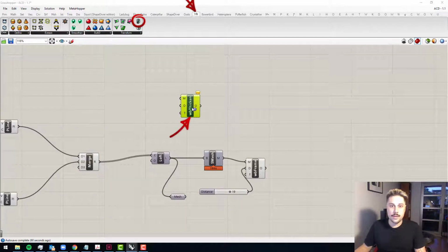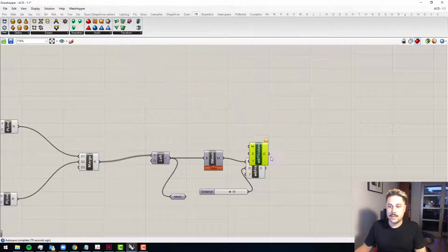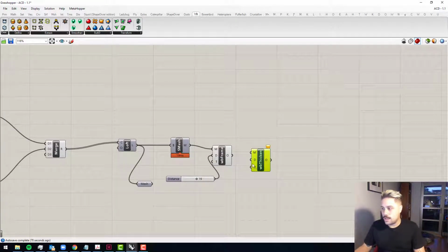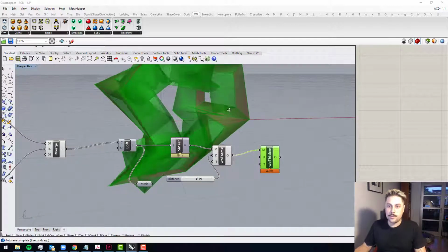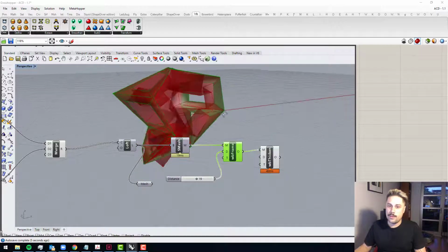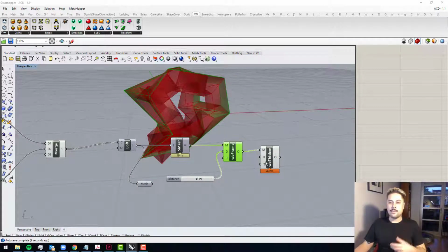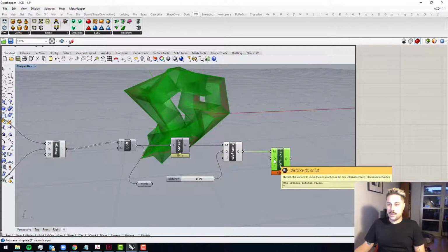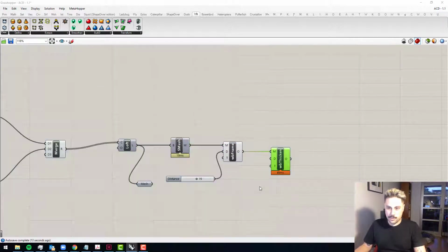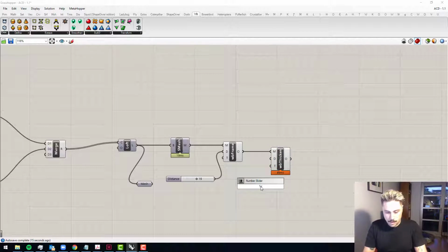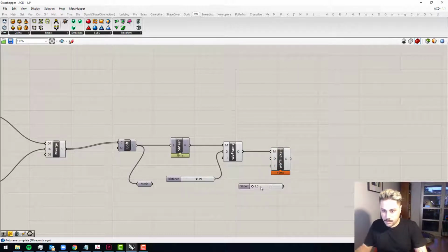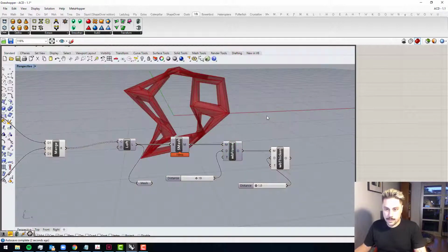Weaverbird's Mesh Thicken. There it is. So this takes our mesh that was one face and offsets all those faces in, so extrudes it all in, and caps all those extrusions off. And that's done it by about 5. We probably want to do it by about, I don't know, we'll go 4. Cool. And we'll turn that off now because we don't really need it.